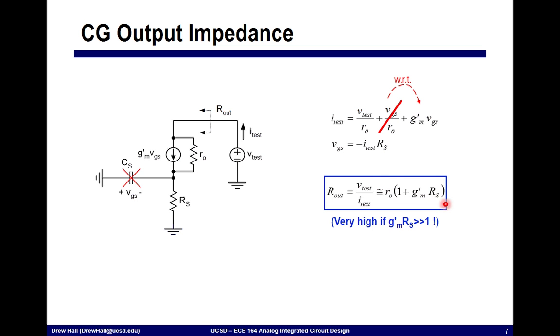Okay. So if we think back, we've actually seen this before. This exact same circuit, identically the same circuit, we analyzed when we were looking at a common source with source degeneration, and we found the exact same answer. Okay. And if we think back, I've hinted at this a few times, we'll talk about it much later in this course, that this is a form of feedback.